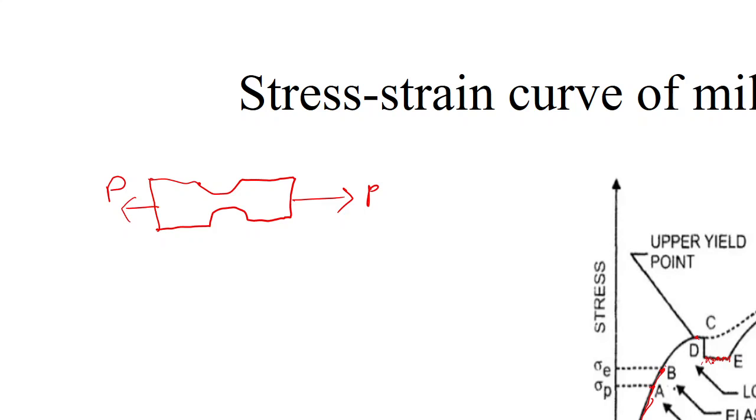The dislocations move and then stay near the grain boundaries, and once we give further loading, the dislocation starts moving again. So there is a continuous drop and rise in the value of stress during this region. But for design purposes we will take the upper yield point as the yield stress value for mild steel.